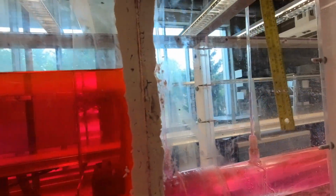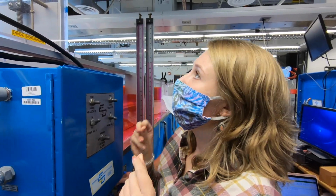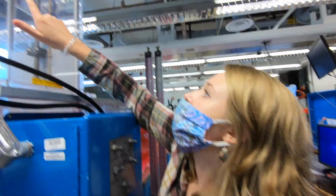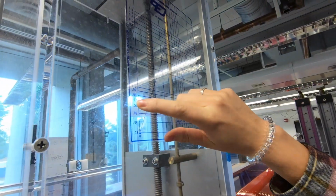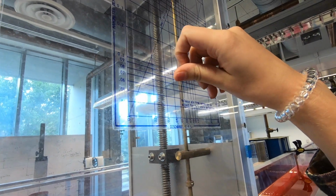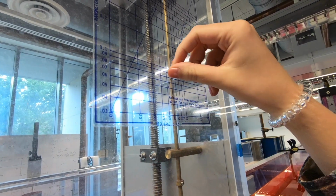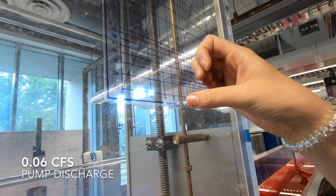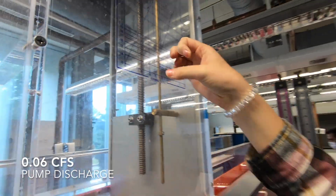So for trial one, our manometer deflection was 0.08 feet. So we find that here on this line. You run your finger along the line to the large orifice line, and you read the number right off, and it's exactly 0.06 CFS.